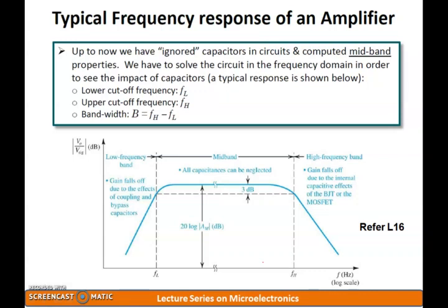That's very interesting and very important whenever we talk of an amplifier, because we don't want our amplifier to be limited to a very minimal frequency. We want any amplifier to work at the highest frequency without any drop in the gain. To ensure that our amplifier works at a constant gain in the midband, I need to understand its higher cutoff frequency, or upper cutoff frequency, FH.